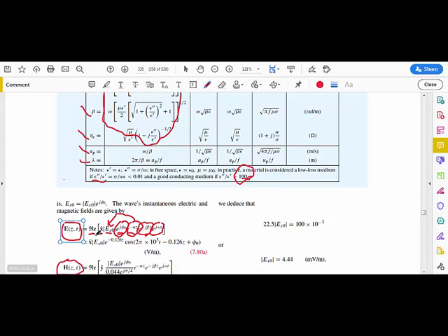So the real part of all of this will be, out of the cosine, the magnitude multiplied by the exponential of the attenuation, which with alpha equal to 0.126 is exponential minus 0.126 z.